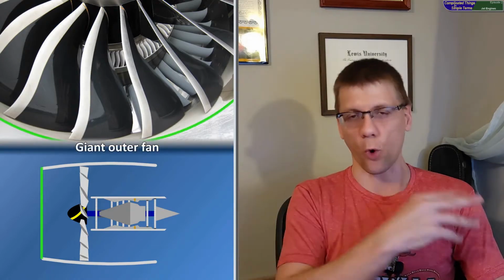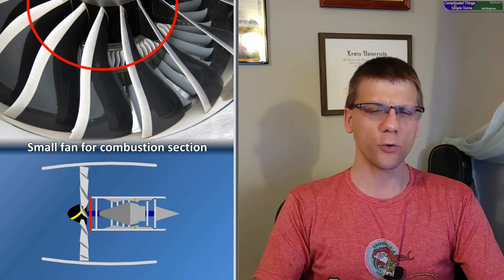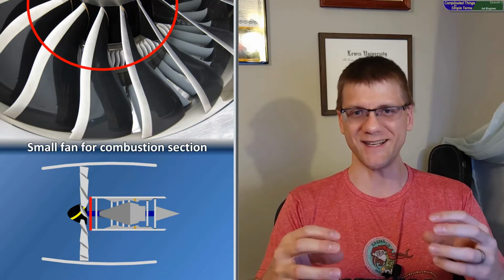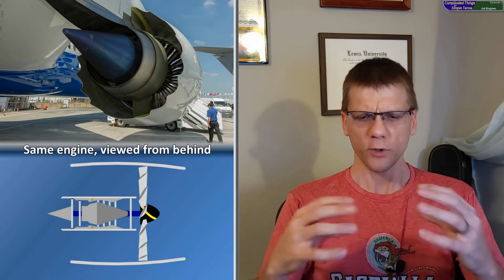Now, in flight, that's not normally a big concern. At 36,000 feet, it's -50 or -60 degrees. It's very cold. But when the plane is on the ground, well, you don't have this wash of freezing cold air going over and through the engine. So an old-fashioned turbojet engine that didn't have the big fan on the front and didn't have most of the air bypassing the combustion section of the engine, well, it would get very hot, and it would be difficult to control that temperature.